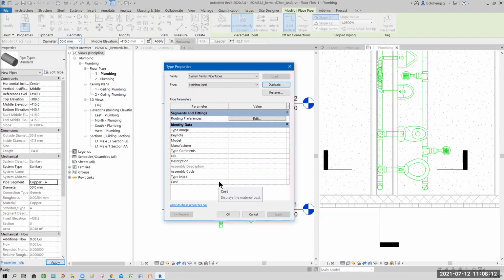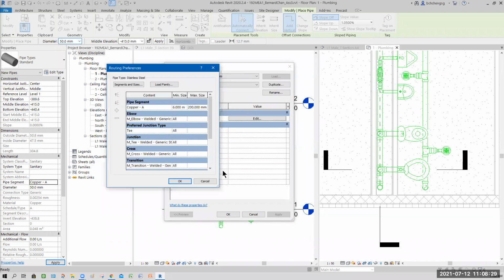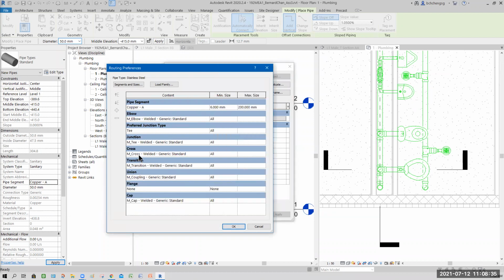You guys are following me? Okay. So when you create a stainless steel pipe, of course, see the route here, edit. So select. Then here is where you can customize whatever things. But of course, all the coupling defaults, we don't have, so I just leave it. So here you can choose stainless steel, which is below here. But I don't know what the quality type is. I mean in Singapore, is it 5S or 10S?